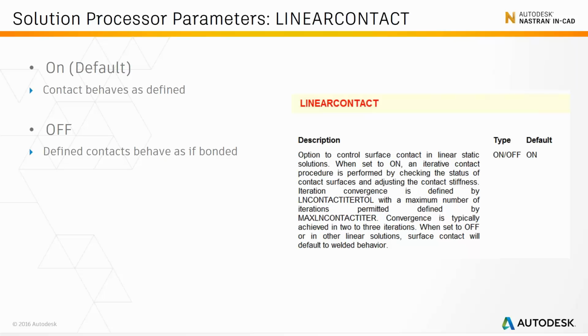So it overrides those contacts temporarily, recognizing that you can switch these on and off to see whether they're having an effect as well. So if you're trying to troubleshoot and understand maybe it is a contact, potentially you could come in, turn this option on, check to see whether the study will solve and the results of running that, and then if it gives you the outcome that you want, turn it back off, and then you can recognize, well, it's helped me identify an area of my model or my setup that needs to be addressed.